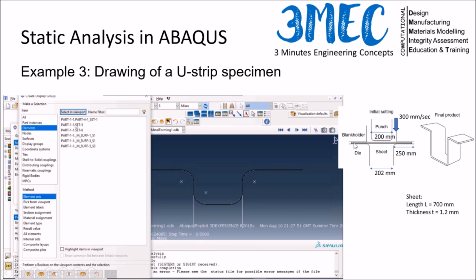You can also find out the blank holder forces by doing this exercise. You can also estimate the capacity of the punch press which is required to form this kind of material. Another important thing is, since it's formed, now if I move it back, in reality you have an elastic spring back, so it will not stay there, but there is a spring back which will try to move the structure back slightly up. So you won't get the actual geometry, but it will deviate from it. In reality, when you are designing the process, you have to compensate for that elastic spring back, and maybe you need to form it more so that after the spring back, it goes to the actual geometry.